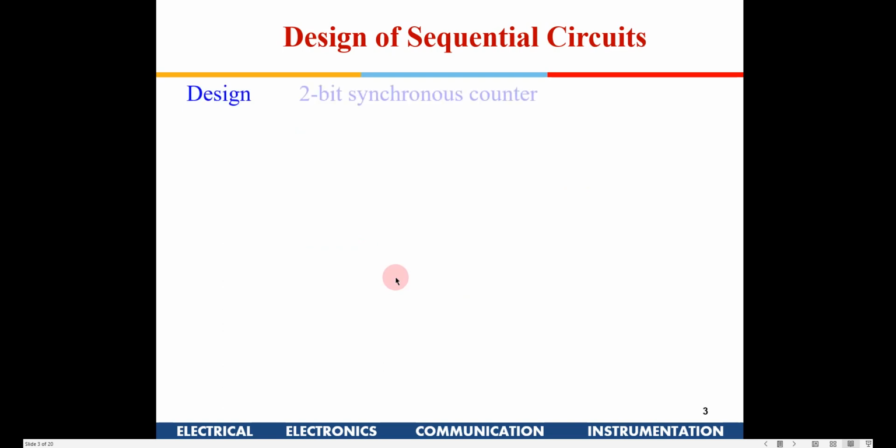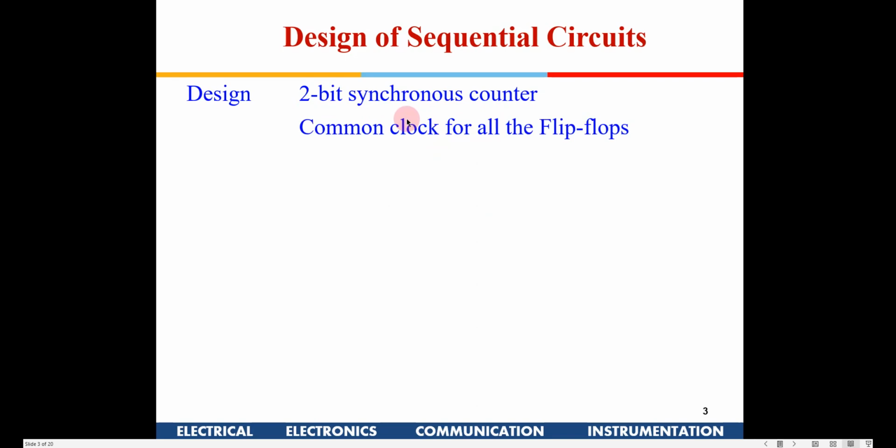So if you see here, let's take an example of making a 2-bit synchronous counter. When I say a synchronous counter, it means that all the flip-flops we are going to use in this design will have a common clock, the same clock applied to all the flip-flops.